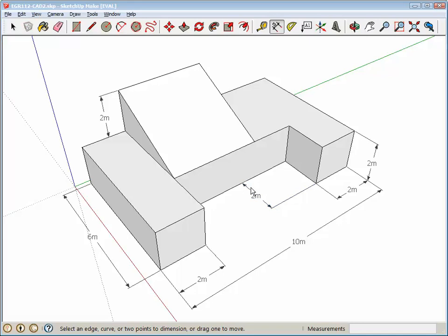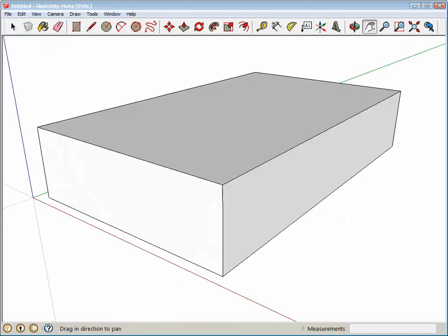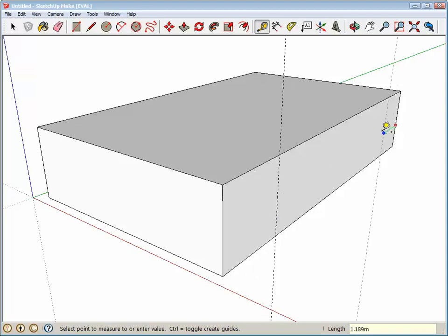We're going to do a 2 meter cut in, 2 meters from each edge like that, and then add a wedge over here. And I believe this is 4 units across like that. One way we can measure that, oh, well, I'll get back to that in a second. Let's go ahead and do the 2 by 2. Grab the tape measure tool, select here, move in that way just a little bit, then type in 2M. Do the same thing on the other side, come in this way, type in 2M, enter.